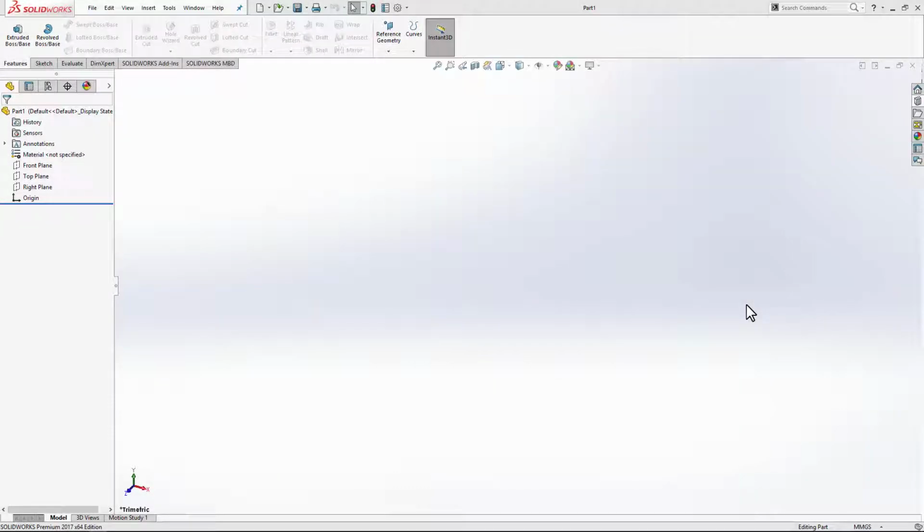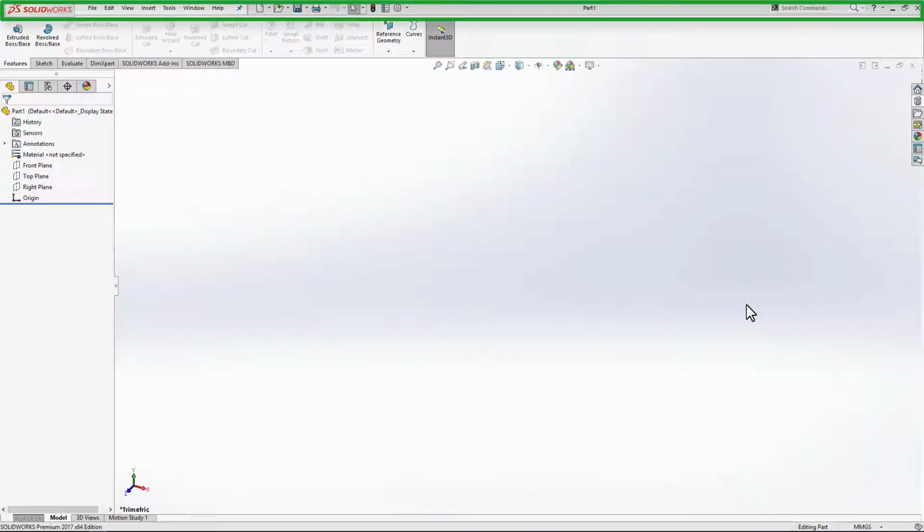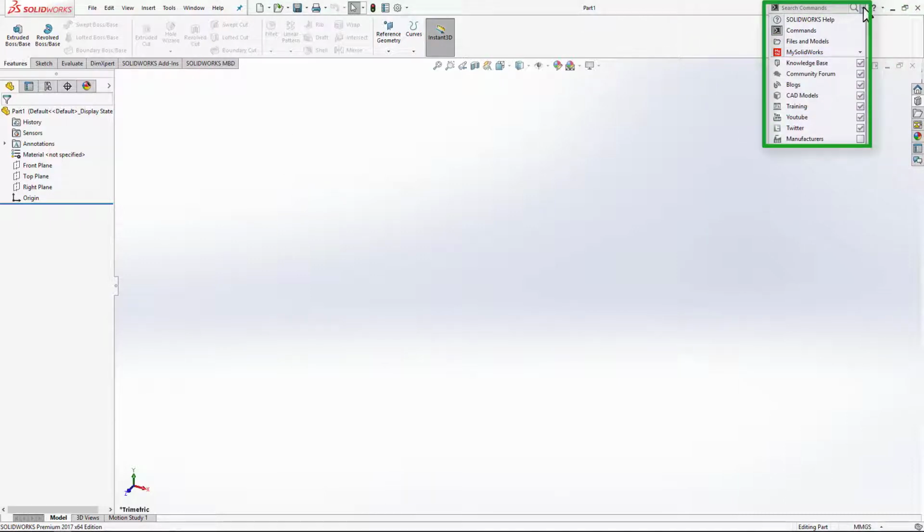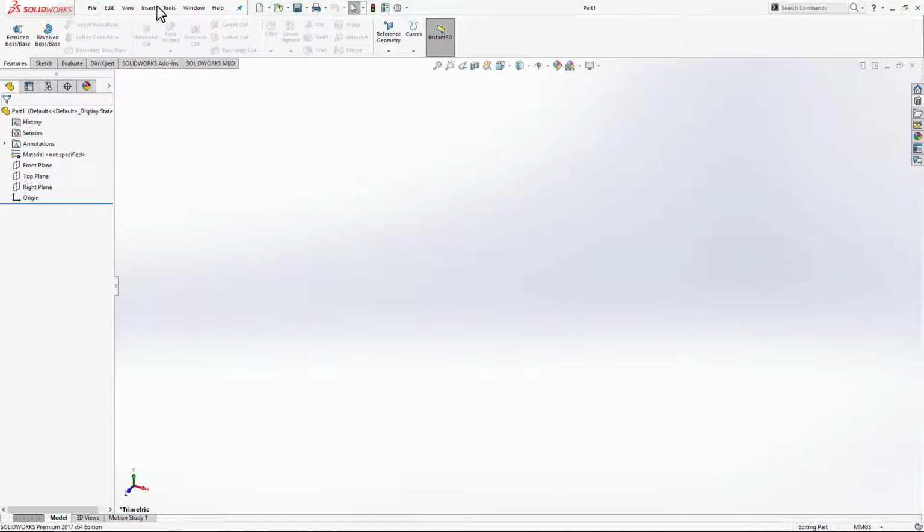In the user interface, we have Menu Bar. The menu bar contains a set of the most frequently used tool buttons from the standard toolbar, the Solidworks menus, the Solidworks search, and the flyout menu of help options. The menus are visible when you move the mouse over or click on Solidworks logo. Use this pin to keep them visible.